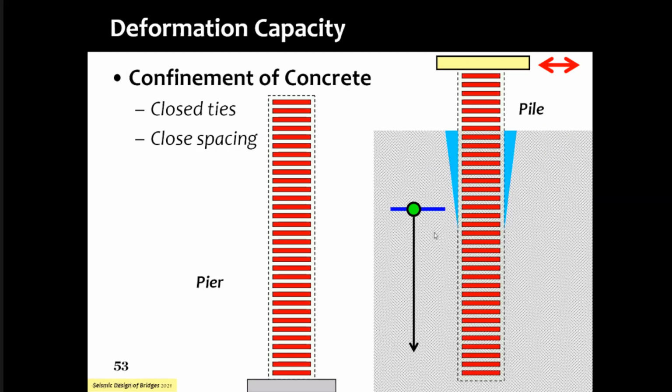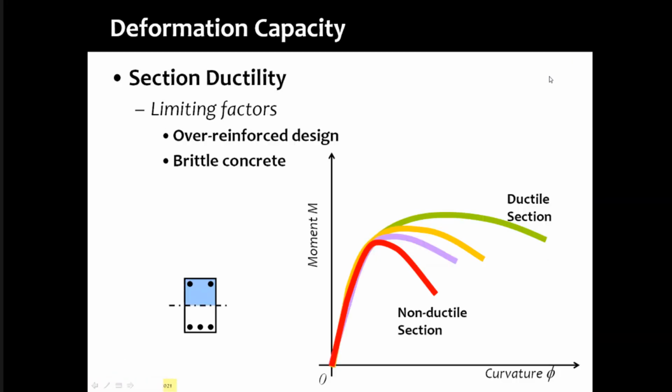So you are going to see that the best option for you is, because you don't know this, first of all, there is covering, which can be 20 meters. Secondly, there is also the issue of loss of contact, which can be 5-10 meters. So in a 40-50 meter pile length, you can lose 30 meters just like that on the basics itself, which means that you don't have the luxury of doing selective detailing. You have to do uniform close spacing throughout the height of the pile. That is the first lesson that we are learning from this today.